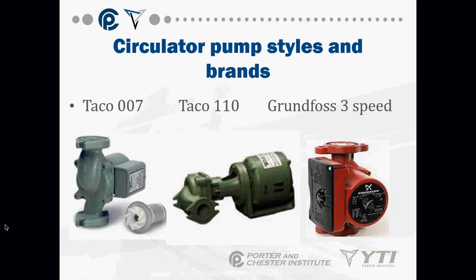beneficial to have. The Taco 110s, these guys are a little bit bigger, a little more massive, where they actually come with three different components. You have your circulator over here, your linkage, and then your motor. What happens with these over time is the linkage actually does fail. They do tend to break, and the circulator happens to fail. Those are usually your two most common problems with them.